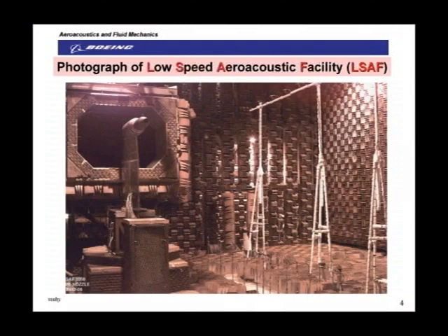This is a jet simulator which can produce two streams of heated gas to simulate high bypass ratio turbofan engines. And the jet simulator is embedded in a free jet wind tunnel, which can get to a Mach number of 0.32, which is higher than the takeoff speeds for most of the aircraft in service today. Also, this jet simulator is incorporated with a 6-component force balance so that you can measure thrust alongside acoustics at the same time.